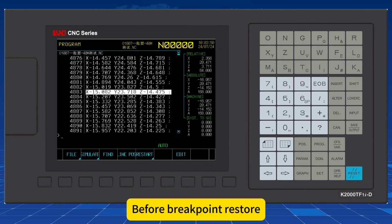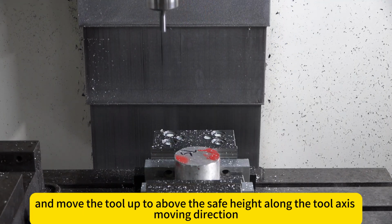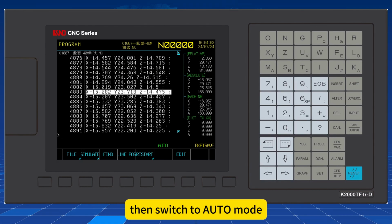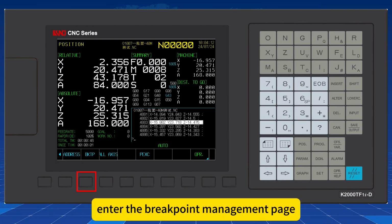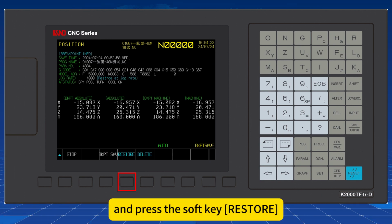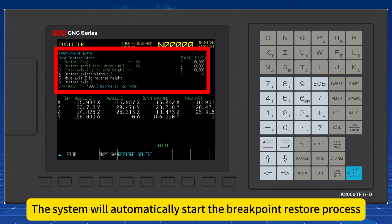Before breakpoint restore, firstly switch to JOG, MPG, home mode, and move the tool up to above the safe height along the tool axis moving direction. Then switch to auto mode, enter the breakpoint management page, and press the soft key restore. The system will automatically start the breakpoint restore process.